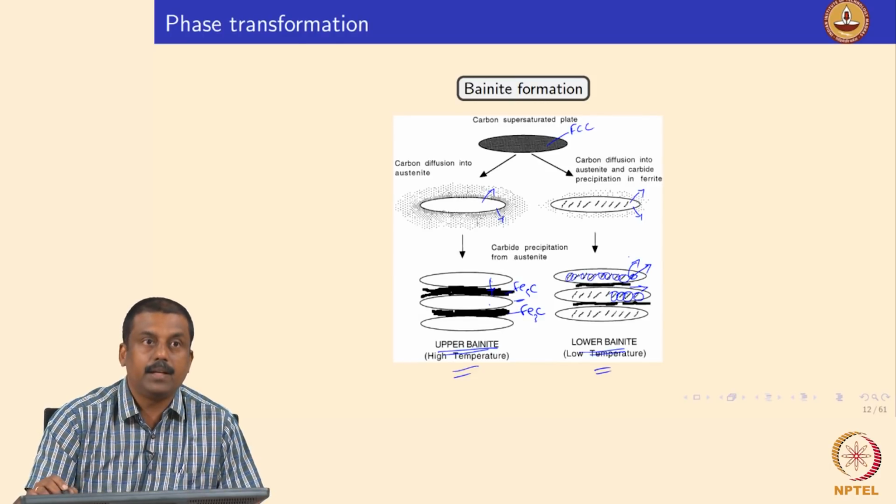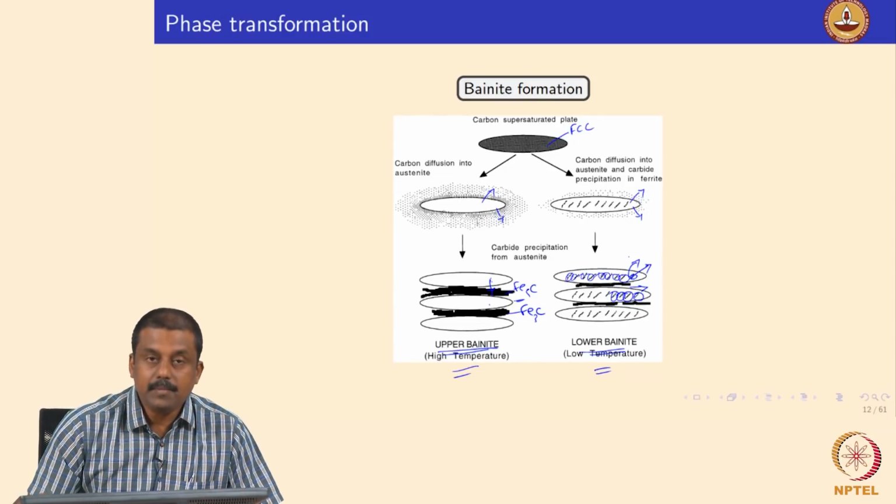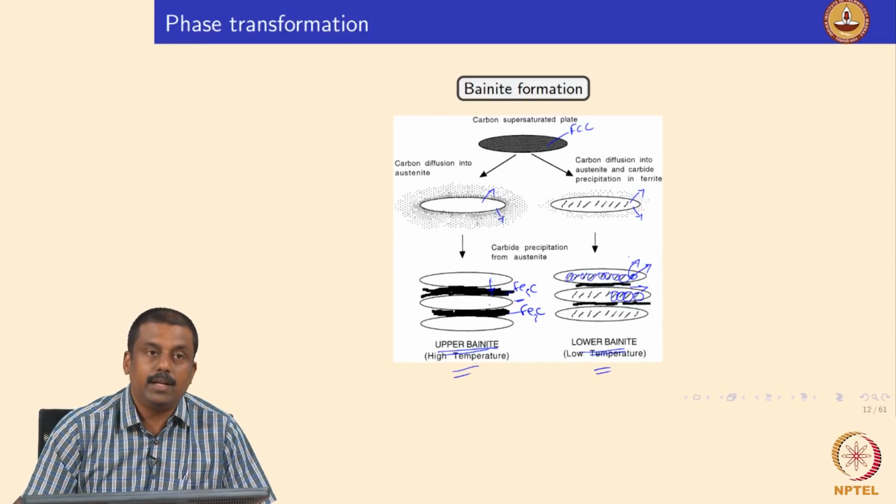Okay. So, with that we would like to summarize what we have learned so far. We looked at the basic iron carbon system, and the importance of the various lines you see in the phase diagrams. We looked at the regions that are interesting for us in this course, the eutectoid composition, and the carbon in austenite and carbon in ferrite lines. Okay. So, we saw what phases can form under equilibrium conditions when you cool, transforming austenite to room temperature.